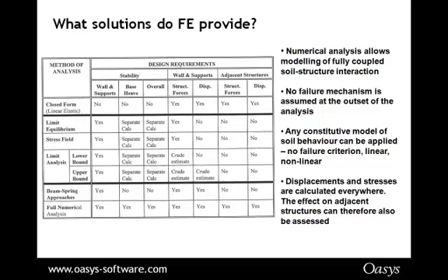It can also deal with complex loadings, complex soil conditions, in that, for example, it uses a constitutive model of soil. So you've got nonlinear models of soil as well, and complex boundary conditions. And the fact that it models time effects and the development of pore pressures is exclusive to finite elements, I think. There's also the case that within finite elements, there is no assumption of a failure mechanism. So there's no failure surface or mode of it. No failure mode is required. So in this case, it's a very powerful tool, and it's very useful for a general geotechnical problem.